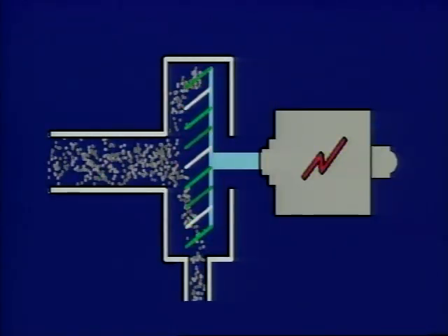This heavy water meets ordinary water in a heat exchanger. The two waters don't mix in the heat exchanger, but the heat causes the ordinary water to boil. The steam from the heat exchanger, or steam generator in CANDU terminology, will turn the fan blades of your turbine, and then the turbine turns your electrical generator. You'll need to cool the steam to condense it and send it back to the steam generator. Lake water's handy for this, so a location by the lake is a good idea.